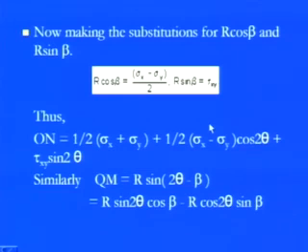If you go back to the figure, which is a Mohr circle, you'll find that β is that angle in the first circle, and you can easily calculate β because it is just sloping with the R. So R along the positive slope, R cos β, will give you (σx − σy)/2. In between, σx is this, σy is this, so (σx − σy)/2, and the τxy, the vertical component, will give you the sine of β. So sin β is nothing but τxy divided by R. From that you can easily get cos β and sin β.